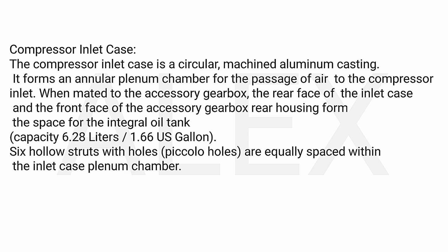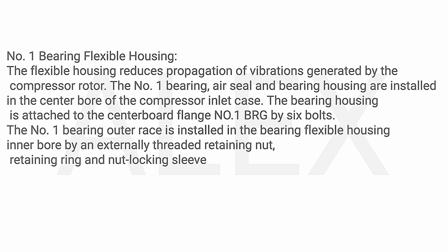6 hollow struts with holes, piccolo holes, are equally spaced within the inlet case plenum chamber. No. 1 bearing flexible housing. The flexible housing reduces propagation of vibrations generated by the compressor rotor.